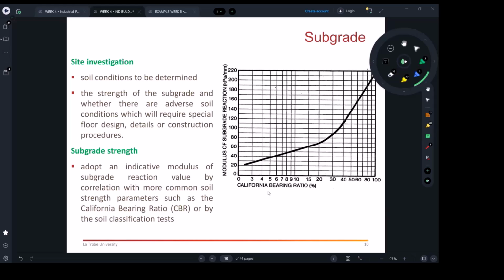Like you see a lot of old houses where developers who got the money want to demolish it and build new units. One of the key things is to make sure there is no main easement, because if there is an easement with about 1.5 meter diameter pipe, imagine that most of that land is filled. And then what does that mean to the developer? It's going to be a very costly footing system.